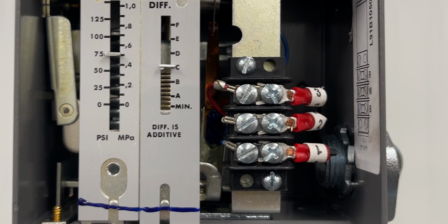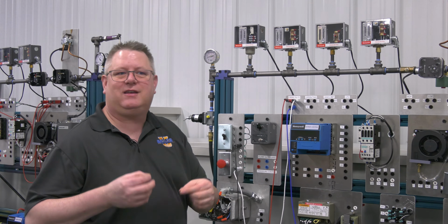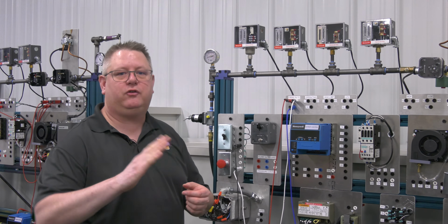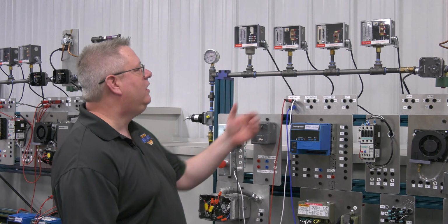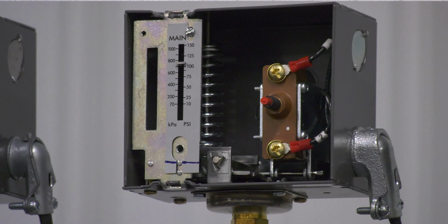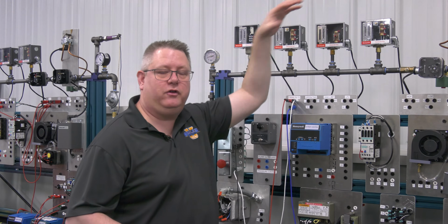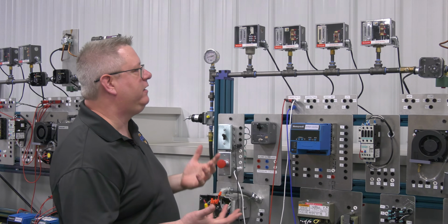Our firing rate control typically has 3 thin wires going to a potentiometer and wiper, and as such, it's not even technically a switch. It's a proportioning control. So if we take the cover off and look at that, we can see it doesn't have a switch mechanism like the other devices. Our high limit is easy to recognize because it's got a manual reset button. And on the new Mercury Freestyles, that's on the front. And on the older Mercury styles, it was frequently on the top. So you may need to get a ladder to verify on a larger boiler that particular switch.